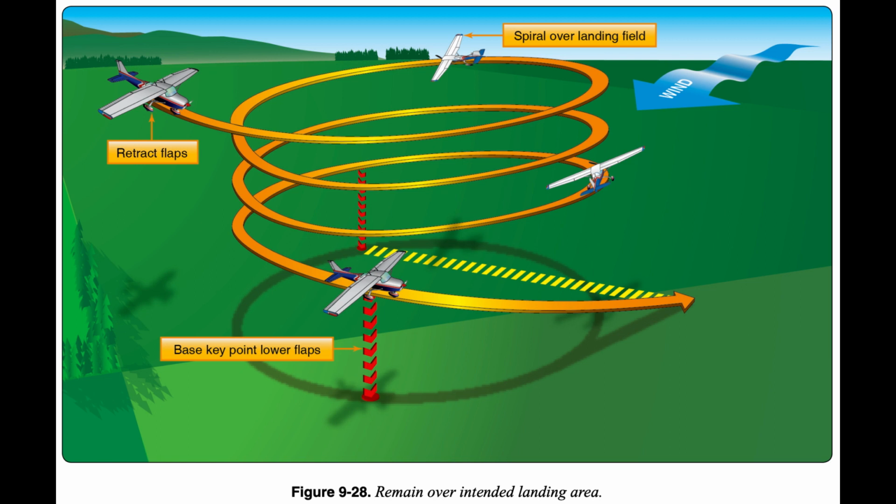Figure 9.28. With the greater choice of fields afforded by higher altitudes, the inexperienced pilot may be inclined to delay making a decision, and with considerable altitude in which to maneuver, errors in maneuvering and estimation of glide distance may develop. All pilots should learn to determine the wind direction and estimated speed from the windsock at the airport, smoke from factories or houses, dust, brush fires, wind farms, or patterns displayed on nearby bodies of water.